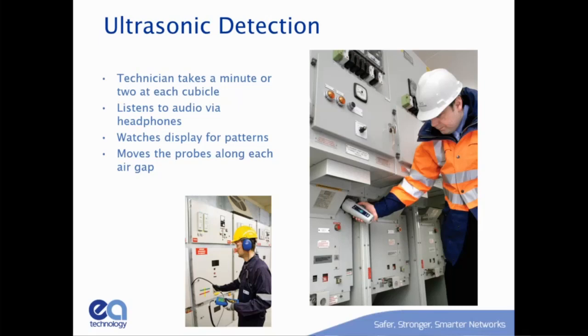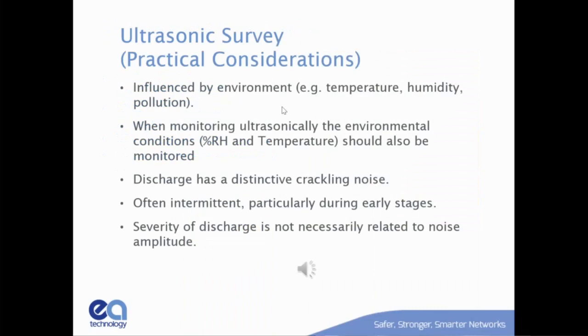So that's an ultrasonic test. We are really worried about temperature and humidity when we do these tests, because humidity plays a big part on whether the discharge is occurring. When it's very dry, the discharge can actually stop, and when it's very humid, it gets worse.